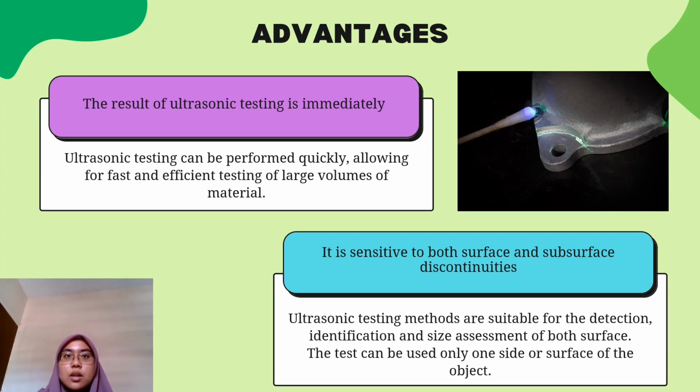The last one is that ultrasonic testing is sensitive to both surface and subsurface discontinuities. Ultrasonic testing methods are suitable for detection, identification, and size assessment for both surface and subsurface flaws. The test can be used on only one side or surface of the object.